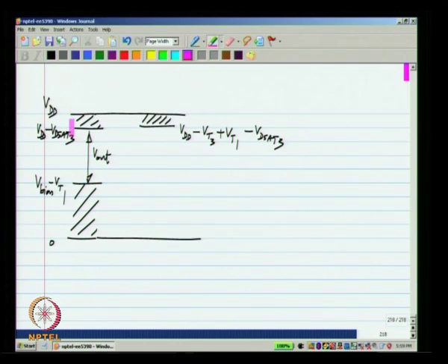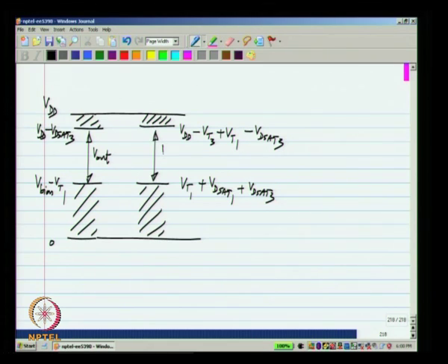It is similar to the upper limit on V out, and on the lower side it is limited by VT1 plus VD sat 1 plus VD sat 3. So, it is very obvious from the expressions that this gap is a lot more than that gap. Okay. So, that is the range for V bias. So, with the particular topology that we have chosen, limits are closer to VDD than to ground.